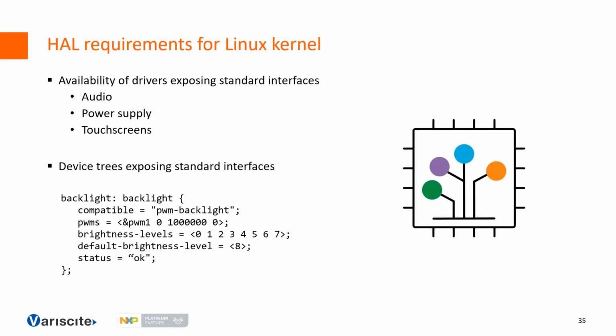So basically, what is happening is that the kernel provides availability for several drivers exposing similar interfaces. So you can mount one codec or another. You can mount one power supply rather than another, one touchscreen rather than another. The point is that from a user perspective, you just receive the audio interface, the power supply management, and the touchscreen interface.